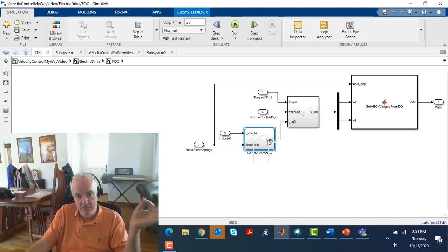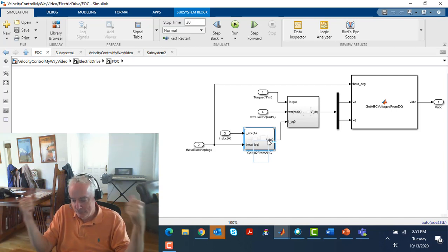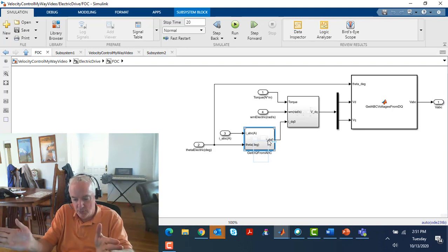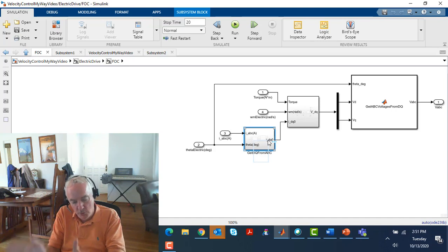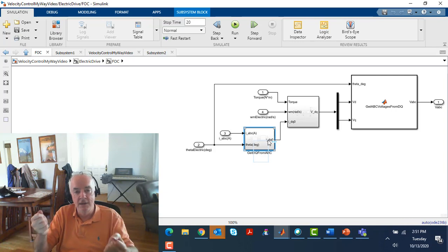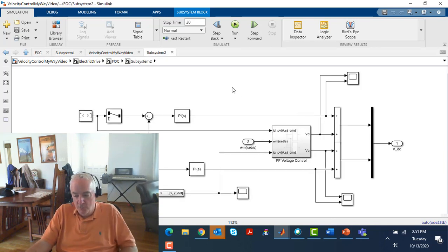It's this idea of observing and expressing your dynamic equations, and there is this vector nature to anything that drives a force or a torque, but viewing it from the perspective of the rotor of the electromagnet. It's through that we get this D and Q orientation, right? And that's quite a remarkable thing.